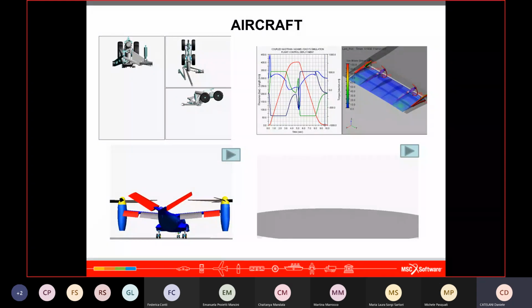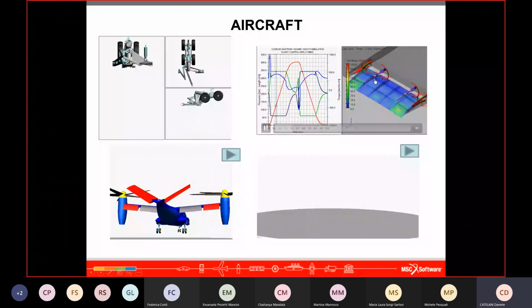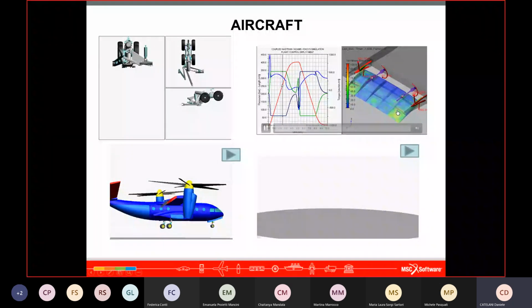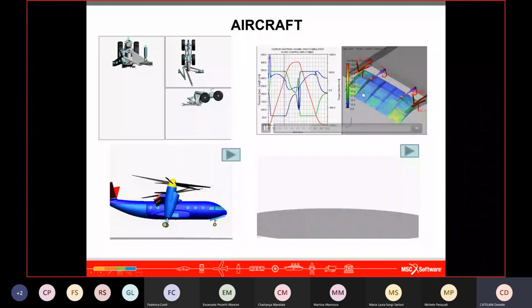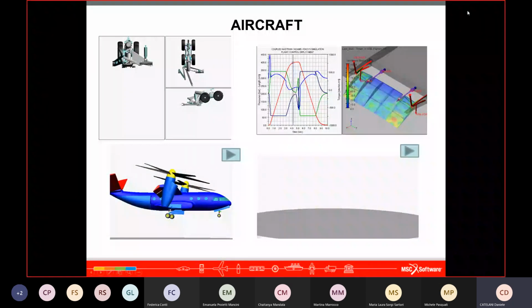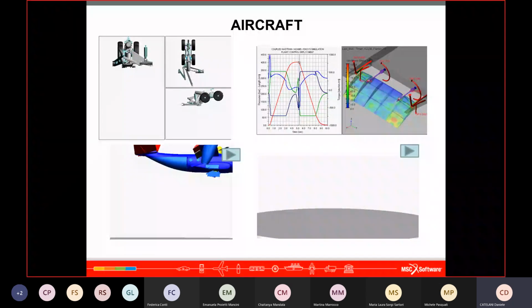During this movement of extraction and retraction, the aerodynamic force changes continuously, and the flap is a flexible body. So you have to investigate a typical dynamic plus structural plus aerodynamics plus controlled system. Again, a multidisciplinary problem driven by multi-body analysis.